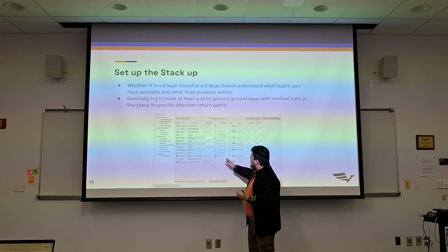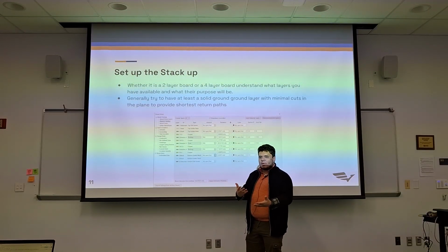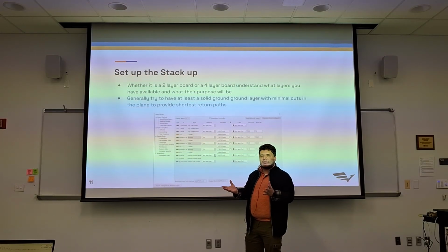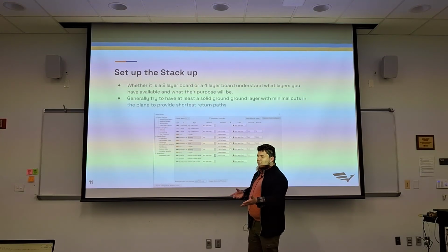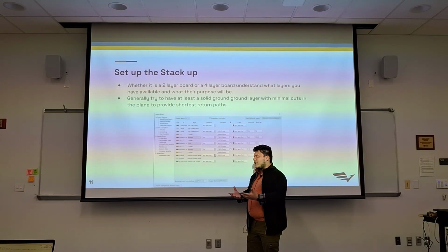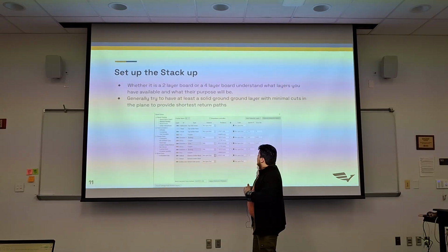Most modern EDAs will have the thickness in ounces. That's how we order our boards, 1 ounce copper, 2 ounce copper. There's a conversion. You can always look up what 1 ounce copper is in thickness. Or sometimes you'll have a stack up that gives you the exact thickness, like before plating and after plating. And so we want to design to that.